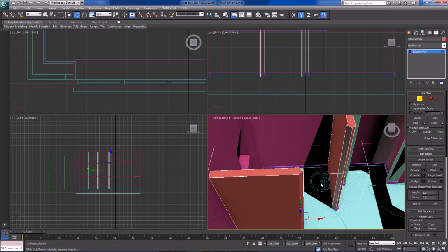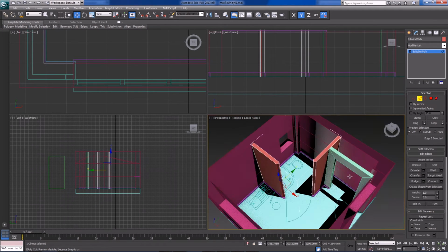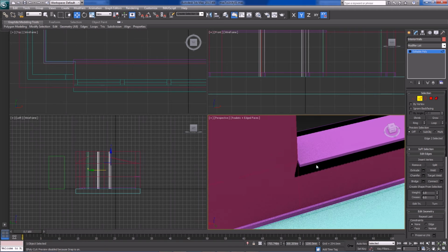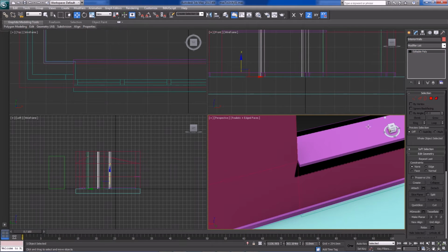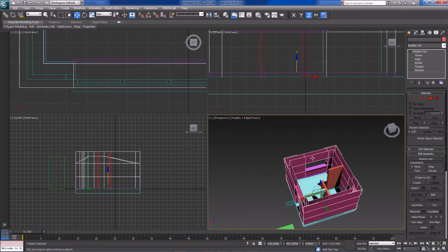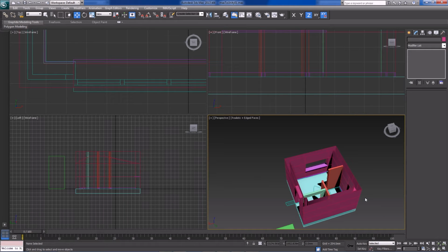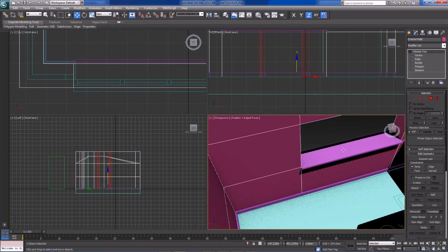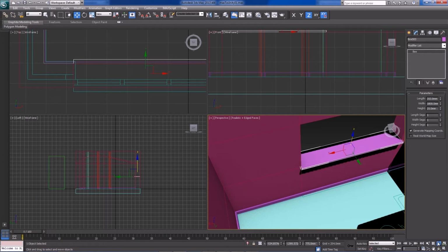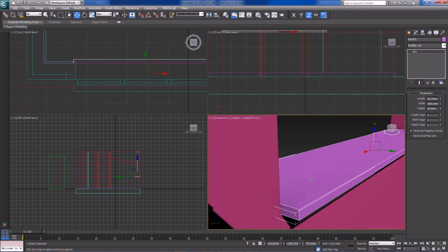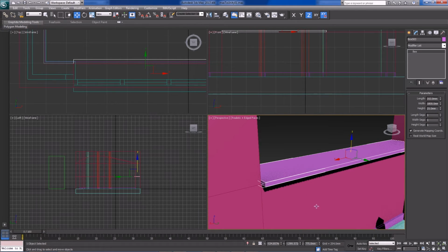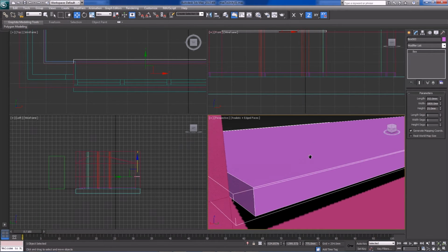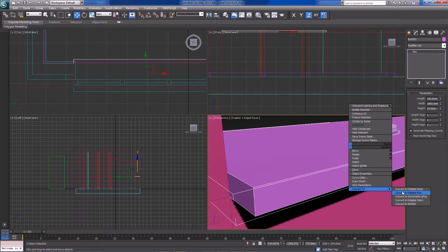Because we are going to be taking this into Unity, we can't go too crazy with this. At least I wouldn't recommend it. It might be unnecessary on the actual, what we would call level geometry in this case, which would be the exterior walls and floor, etc. But because this is an object, as this is separate from the confining walls, and it's probably going to have a material with a specular on it, I would chamfer the edges just a tiny bit.